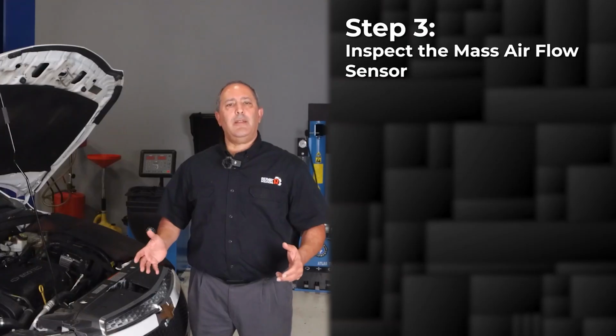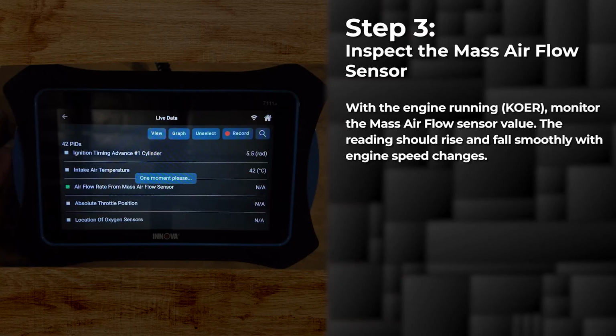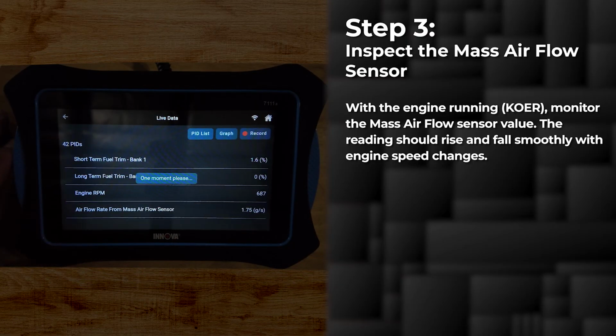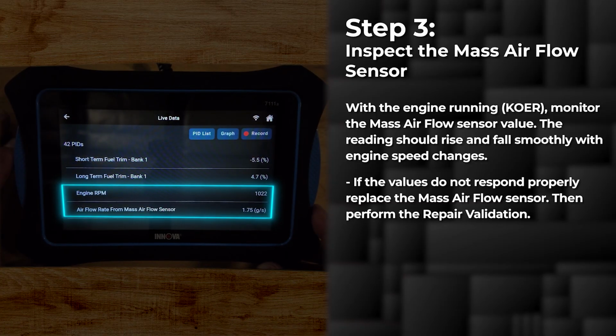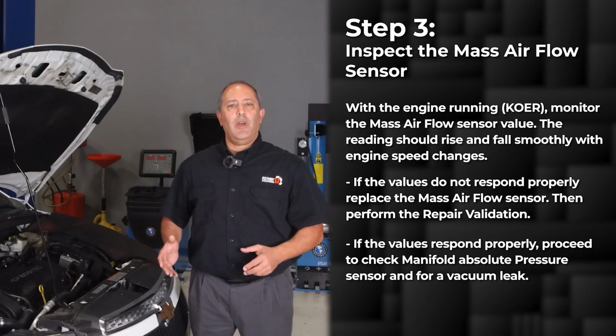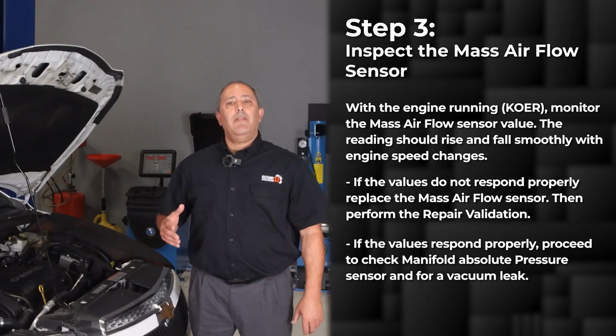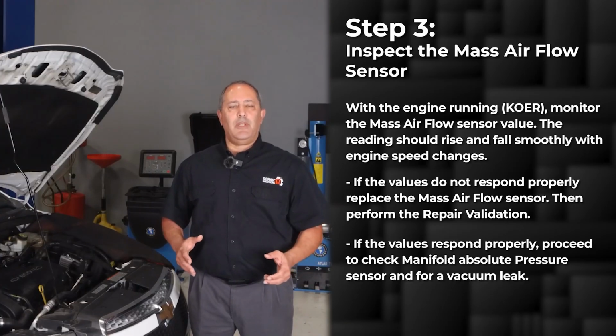Step 3. Inspect the mass airflow sensor. Start the engine and place the ignition in key on, engine running. Monitor the mass airflow sensor data using a scan tool. Under normal conditions, the sensor reading should increase and decrease smoothly as engine speed changes. In this case, the mass airflow sensor signal does not respond properly, confirming a faulty mass airflow sensor. Replace the mass airflow sensor and perform the repair validation. However, if the mass airflow sensor values respond properly and the voltage remains within specification, continue to check the manifold absolute pressure sensor and for vacuum leaks.